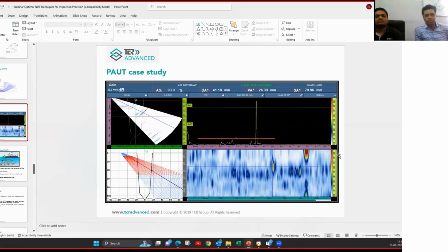The other way is that you do the water fill test. If it is a higher density fluid, then we fill the water and then do the inspection. So in both cases, corrosion, or some minor cracking which occurs because of the corrosion, can be detected by acoustic emission testing in one go. So it is more effective.